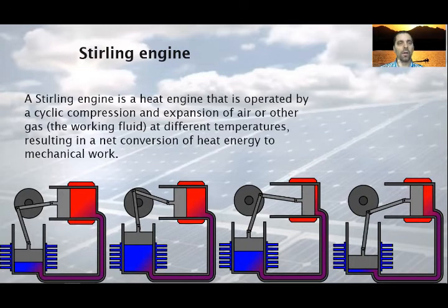Two. The system is at its maximum volume and the gas has more contact with the cold cylinder. This cools the gas, lowering its pressure. Because of flywheel momentum or other piston parts on the same shaft, the hot cylinder begins an upstroke, reducing the volume of the system.